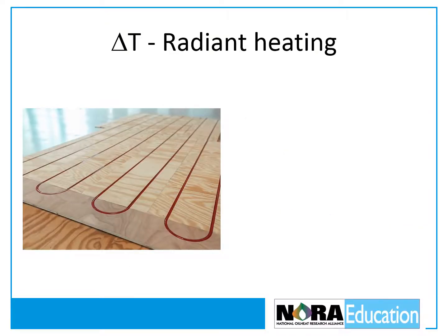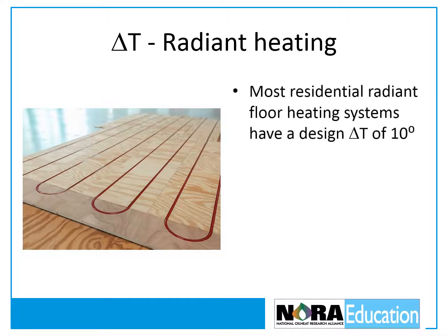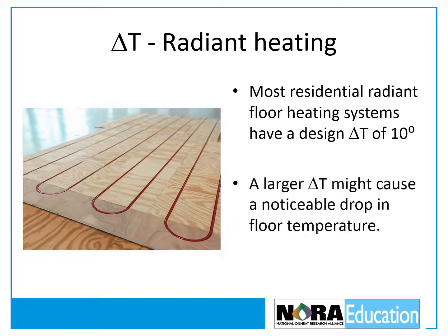Most residential radiant floor heating systems have a design delta T of 10 degrees. Water enters the loop at 130 degrees and returns out at 120. A larger delta T might mean a noticeable drop in floor surface temperature near the end of the run.